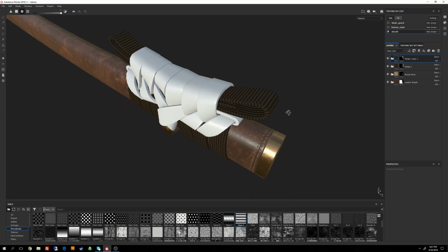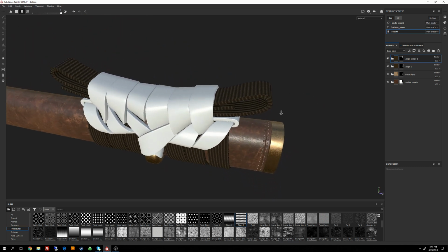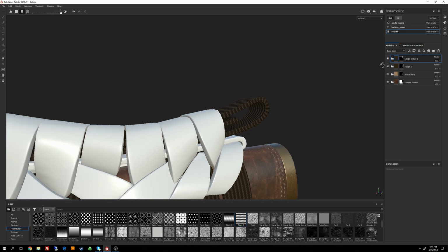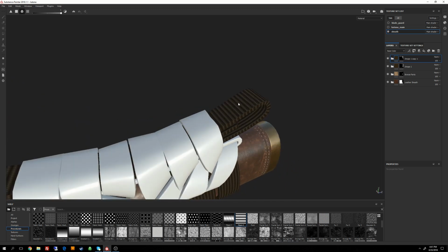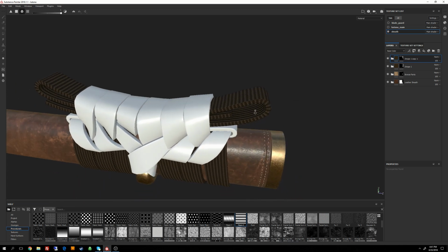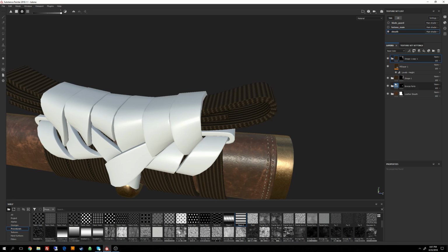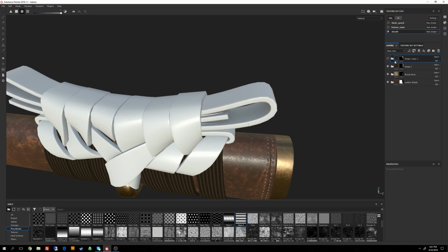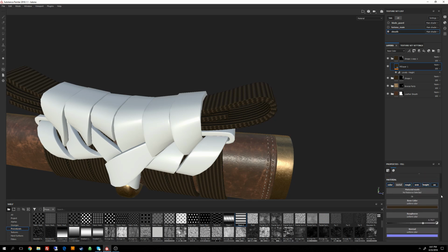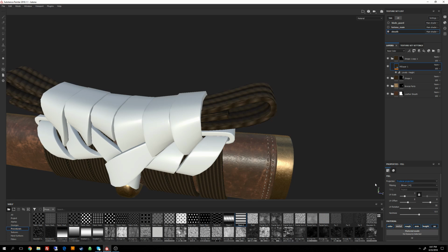And let's see how this texture is projecting on here. And for this one, it doesn't look like it wants to play nice. I'm looking at this, you can see the pattern here is going more horizontally, and then in here it's more vertical. I'm going to see if we go into our material here again, and let's go to projection method and change it to triplanar. See if we can get this all facing the same direction.